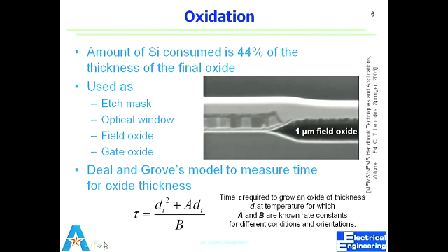Now, while at it, and it's going to come soon. When I was at this step, and I just have silicon dioxide, and I have this opening of photoresist, and we use BHF to etch silicon dioxide, right? So we say, okay, BHF etches silicon dioxide at 1,000 angstroms per minute.